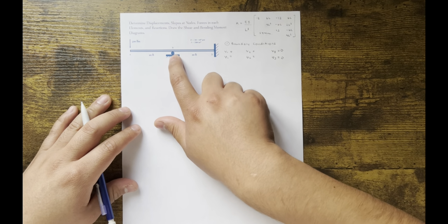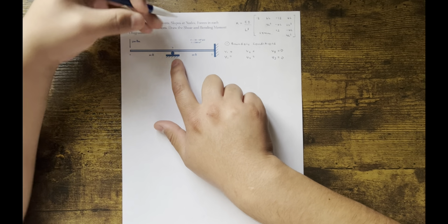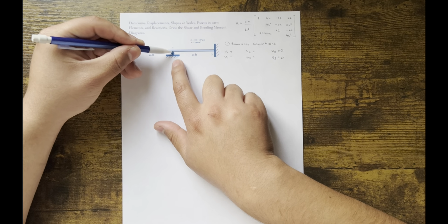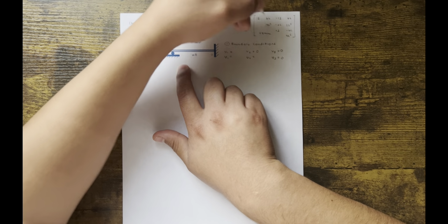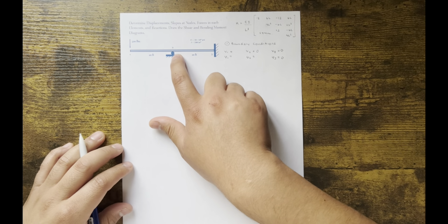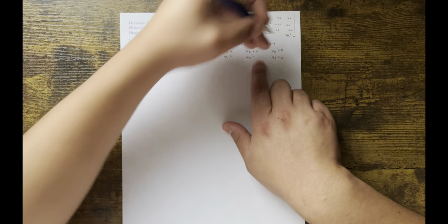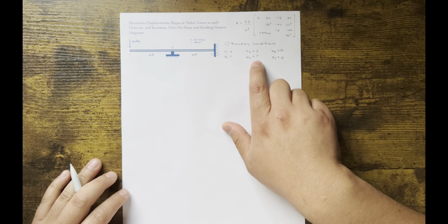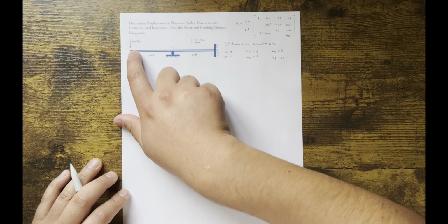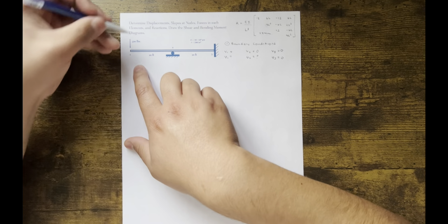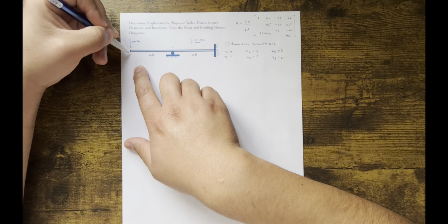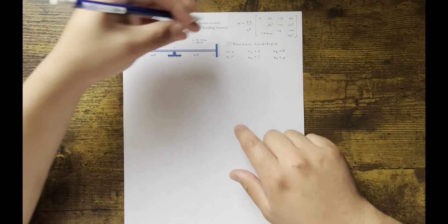We see at node 2, no matter how much force you put here, this thing is holding it exactly, if that makes sense. So that's also 0. That's not going anywhere. But it's a roller, so from statics, you know that there's going to be some angle of deflection. So we're going to put a question mark in this one. And then here, we don't know how much it's going to displace going down, and we don't know what angle that's going to make relative to the axis of interest.